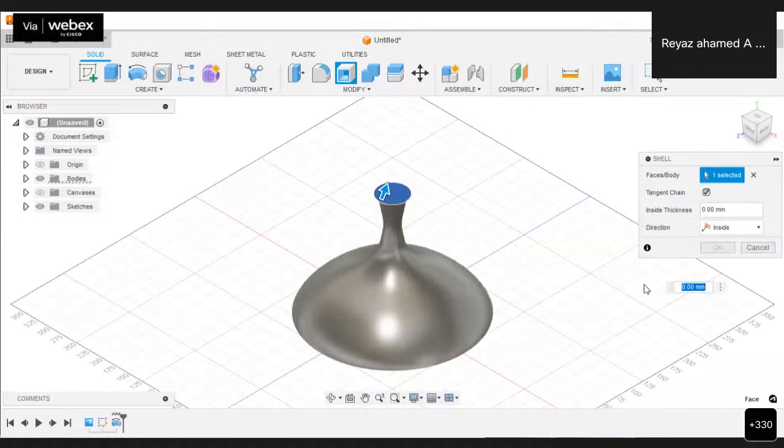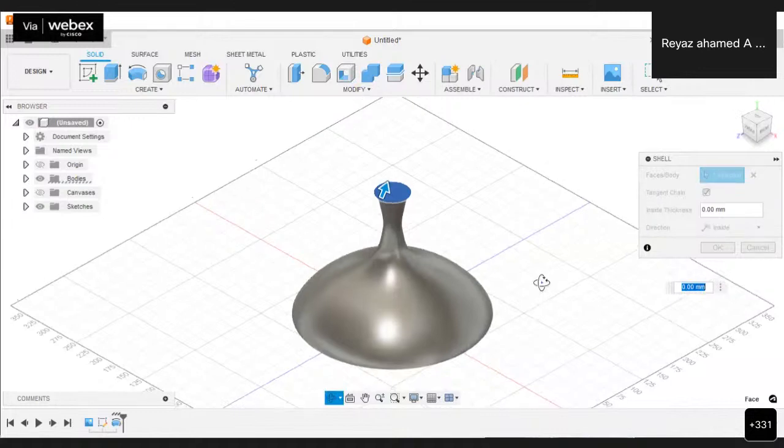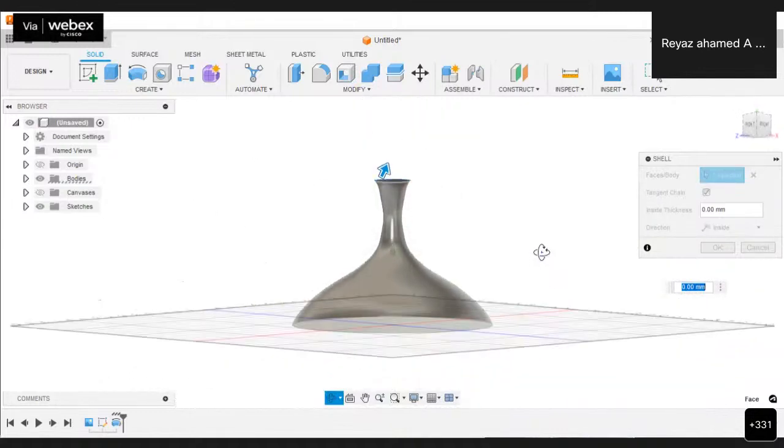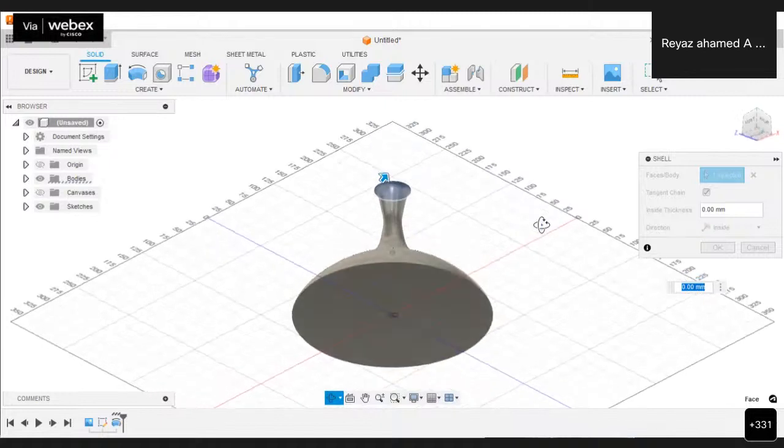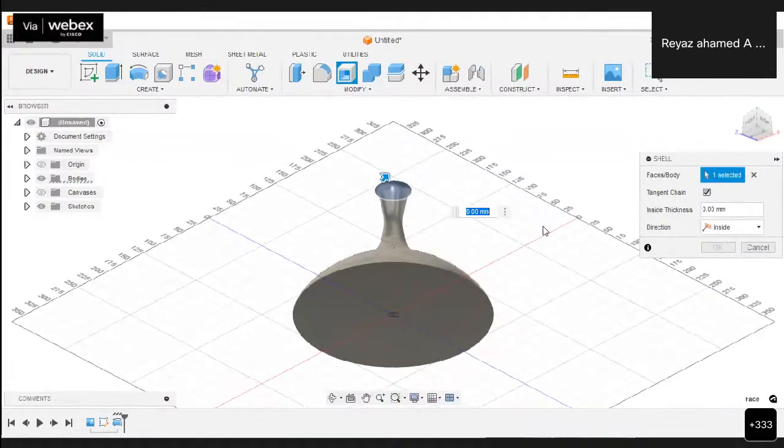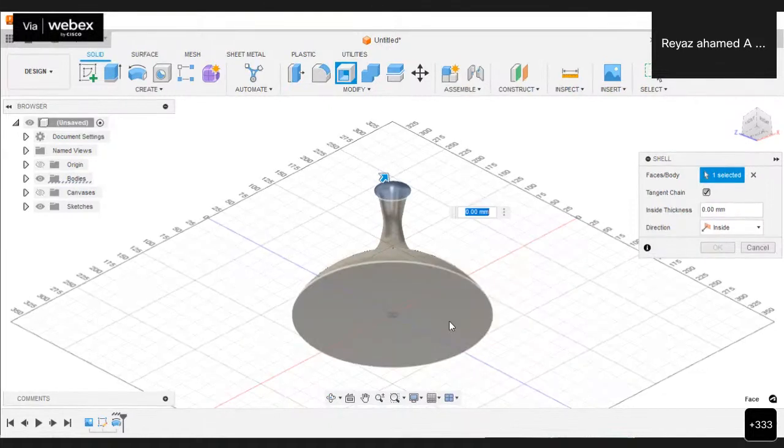And then let me rotate my solid model. For rotation, I already said that I have to press the shift key and my central scroll button. If you press and hold them together, and then move your mouse upwards, automatically the bottom of the object may get viewed. Let me choose the bottom portion also.